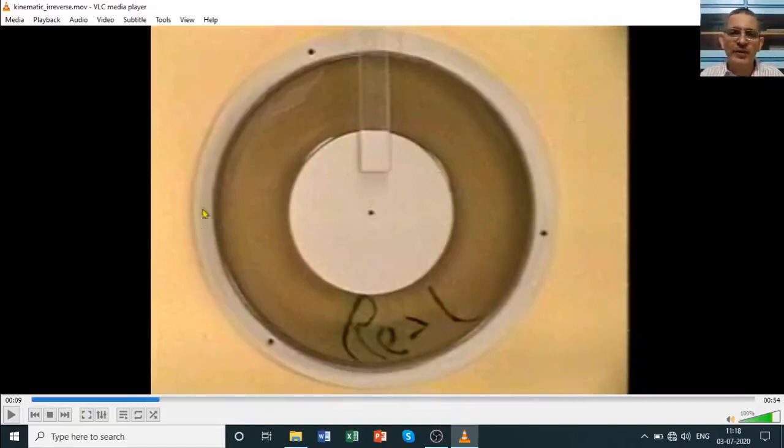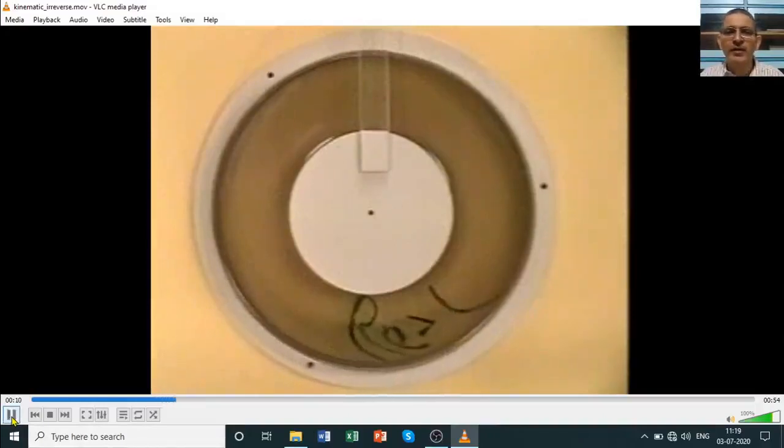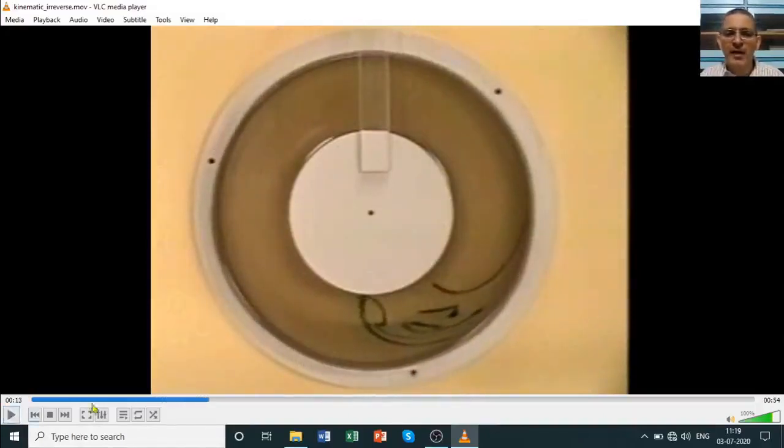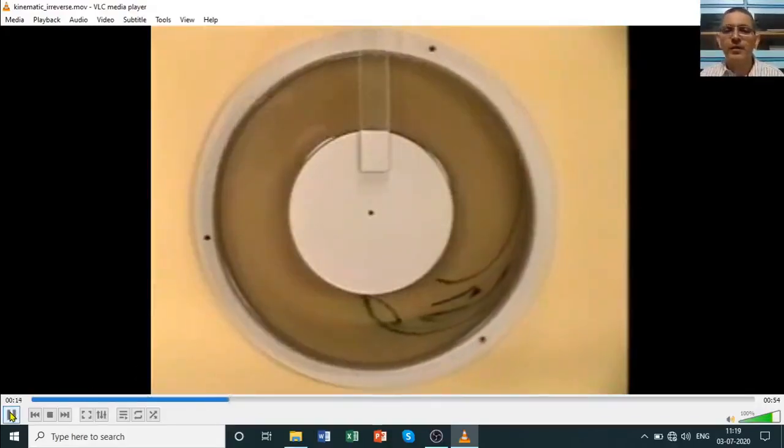And this outer cylinder is going to be turned in the anti-clockwise direction. You will see this outer cylinder moving in an anti-clockwise direction, and because of that, the fluid, this inner cylinder is stationary. The fluid near the inner cylinder is not moving, or is moving very slightly, whereas the fluid near the outer cylinder is moving at a much larger velocity, and therefore the fluid that is in between this region is distorted, and that distortion you are able to see by the distortion of these letters. So you see it getting distorted.